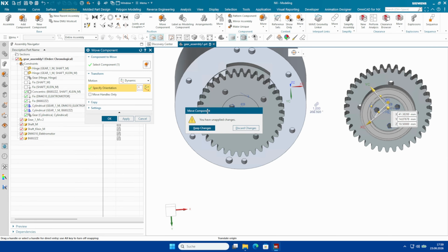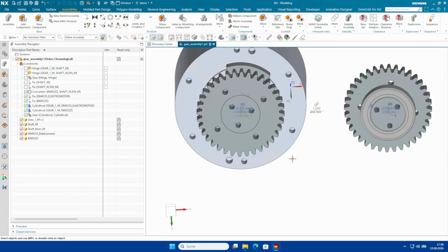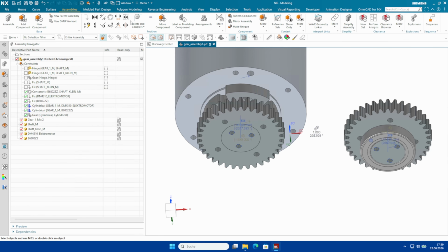I mean, the best thing is just to constrain them to the gears so that they will rotate with them. So what I will do is create bond constraint objects together so that they move as a rigid set. So I'm gonna bond together the shaft and the gear so that they move and behave as one object.